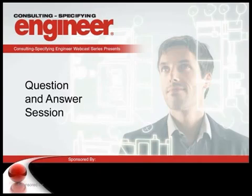Well, NFPA NEC 517.30 actually deals with how many transfer switches you have. If you have a small building, like a small hospital or surgery center, and you have less than 150 kVA worth of essential system loads, you can do one transfer switch.